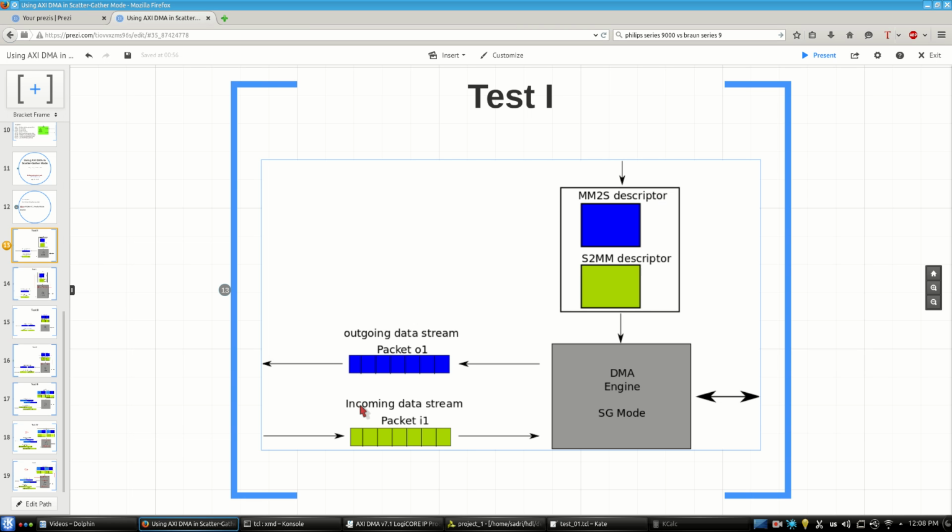As I told you, in the AXI stream logic that I create, everything appears as packets. I put a series of data one after another and create a packet out of them. It's not the case that my AXI stream logic produces pieces of data one after another without indicating the boundary of the packets.